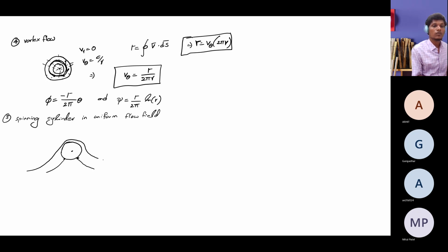And if you draw the remaining streamlines, they look like this. You see the turning of the streamlines. If the streamline is turning with a small radius of curvature, and if it is a fast turning, then it's a kind of rule that velocity is very high at that point. Based upon the curvature of the streamline, you can decide that the velocity is very high at that particular point, and it's in the direction tangential to the streamline. So this is how your flow field looks if you impose this vortex in the flow over a cylinder, the kind of situation that we saw before.